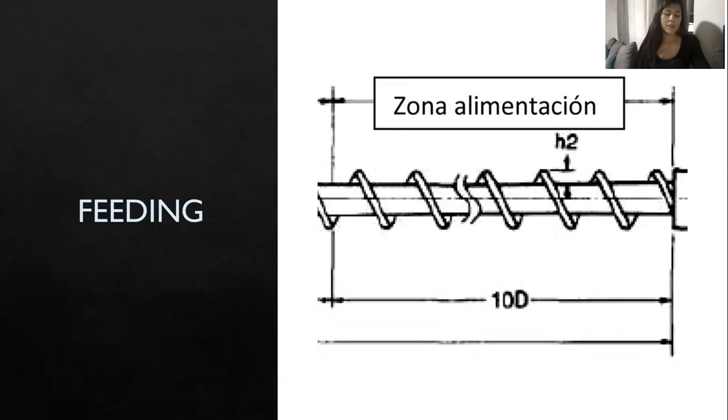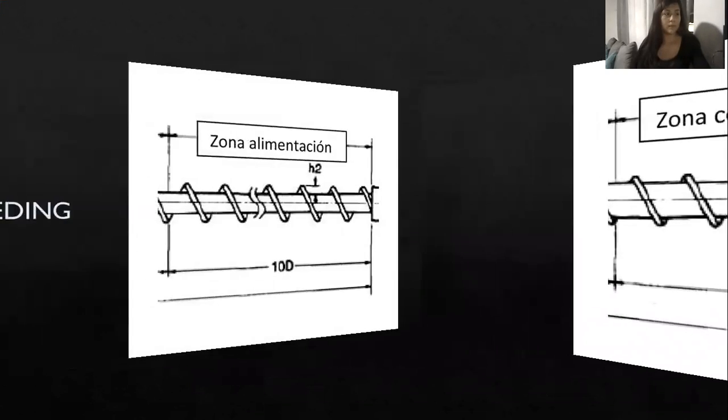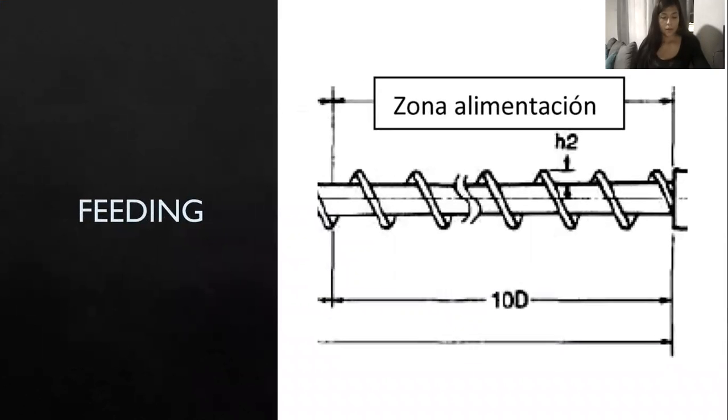We will start with the feeding area. To understand the transport mechanisms of the extrusion spindle, it is important to understand that when the spindle rotates, any materials located between the surface of the spindle and the barrel wall will be transported depending on the direction of rotation.